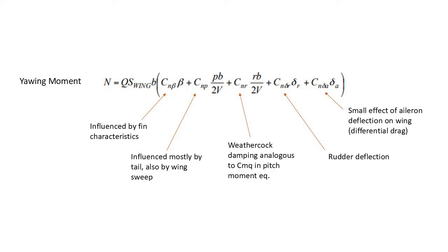If we use winglets on a flying wing, then there's not really a point of using a vertical fin like you'd see in a conventional aircraft. The delta in skin friction drag between a tail, including the supporting empennage, and winglets can still be worth the jump from tail to tailless aircraft, even if we aren't shooting to decrease the induced drag.